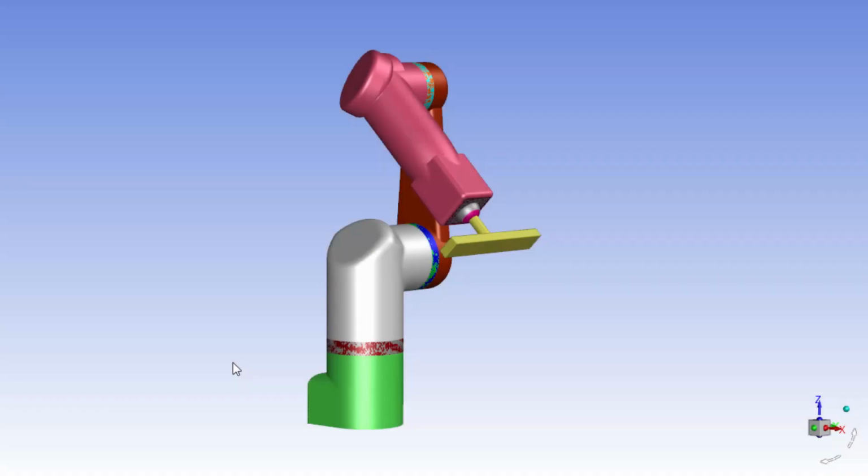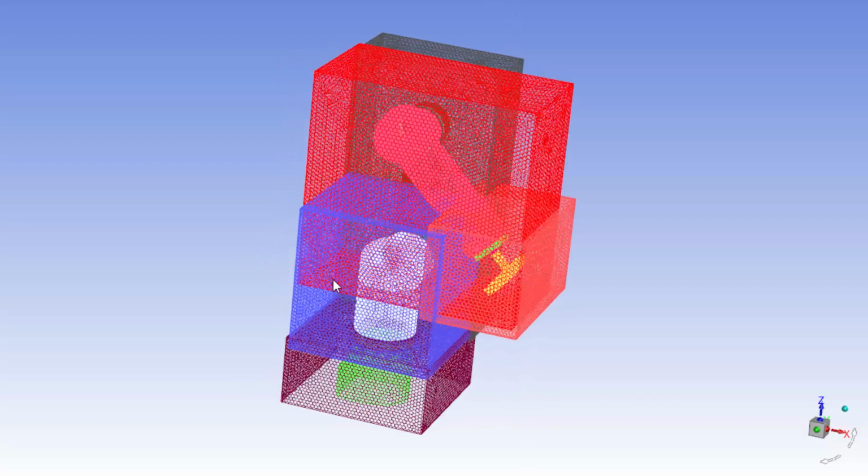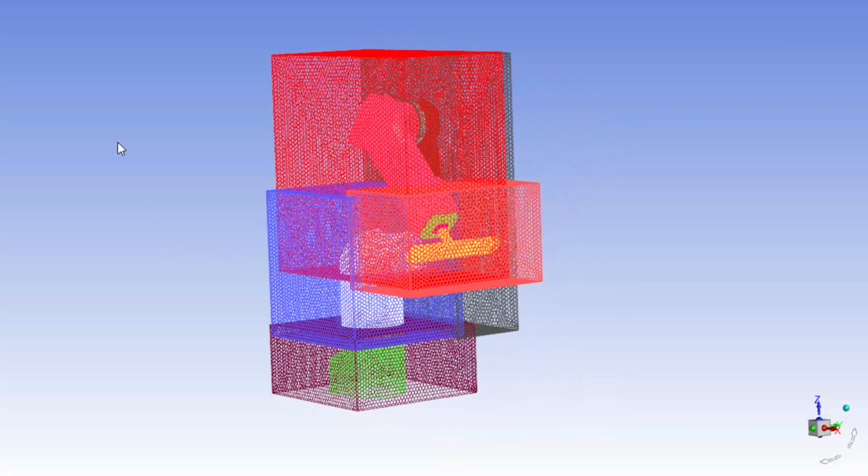I've loaded the background stationary hexahedral mesh describing the room geometry and appended the polyhedral mesh for the robotic arm foot, 3 arm segments, and the end effector. And here the meshes are overlaid. Each overset mesh consists of the robotic arm component wall and its surrounding region.